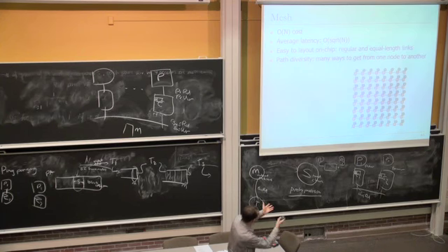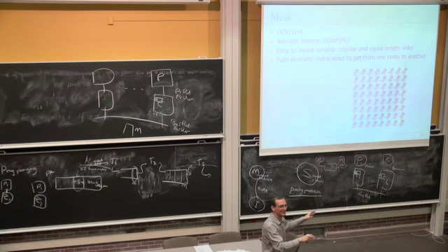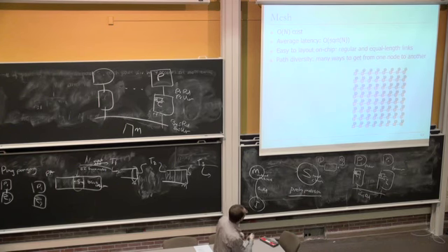Simple, right? Conceptually simple, and you can see that this is easy to lay out also. It's nice. You design one tile and stamp it, and verify only one tile. Cost is O(N). It's not that costly, right? Average latency is square root of N, and you can figure that out. Easy to lay out on chip, and there's path diversity.